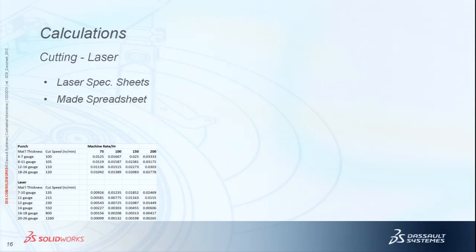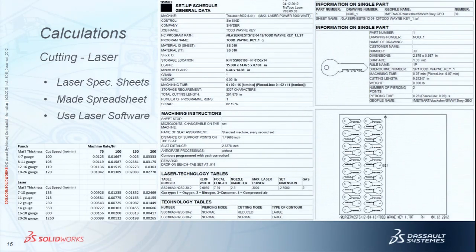And I just did some fictitious numbers because somebody that was supposed to get back to me wasn't getting back to me in a timely enough manner, so I said, well, I want a ballpark. I just did a quick spreadsheet to say, if it can cut this fast and the machine costs this much per hour to run, how much is it costing per inch to cut? Then I can compare that to the laser software, which gives me similar information, and use that as a checkpoint because it will tell me machining time and cutting length. I can compare those to the numbers that I have.